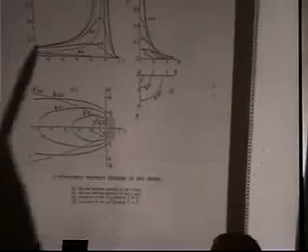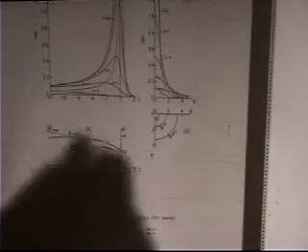If you look at slices in different directions, this is traveling in this direction, and you can see the Gaussian is skewed. If you look in the transverse direction, you actually just see the Gaussian, right? So these are just different values at different times, or different Fourier numbers, or whatever you want to call them. Actually, Peclet numbers. There are different types of dimensionless numbers. Looking down from the top, you could define one of these isotherms as your fusion boundary, and that would be the shape of your weld pool, depending on which one you choose.